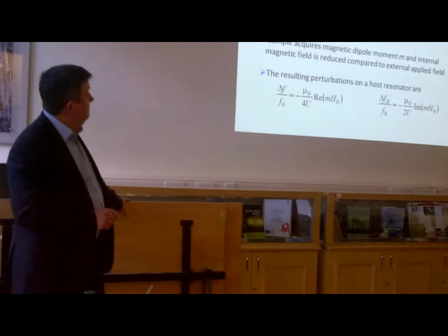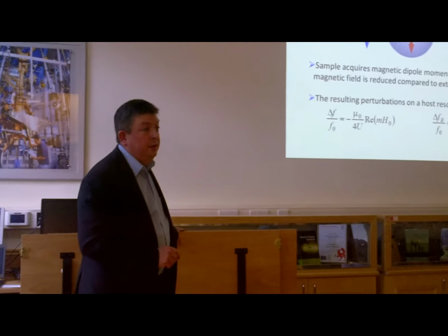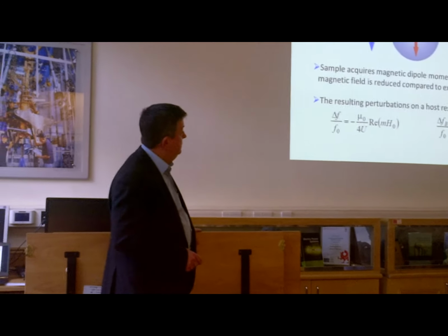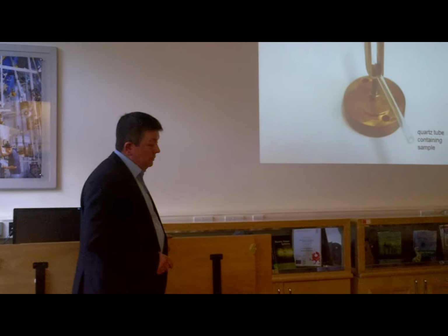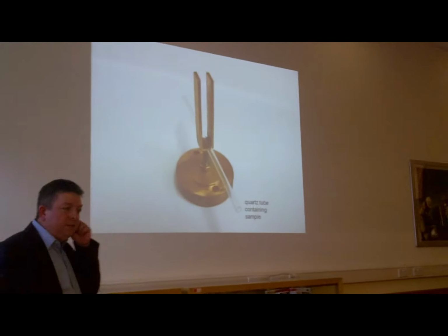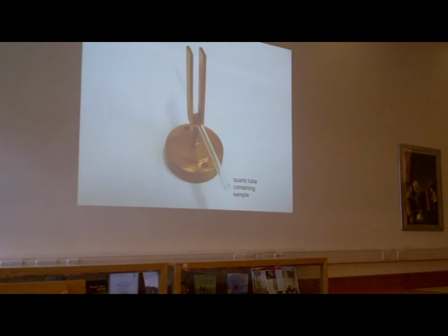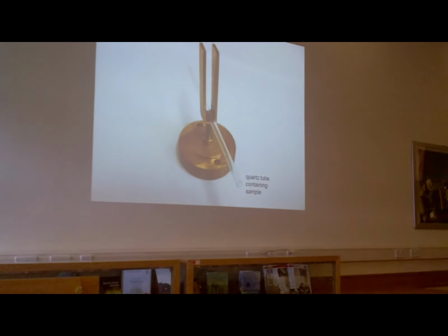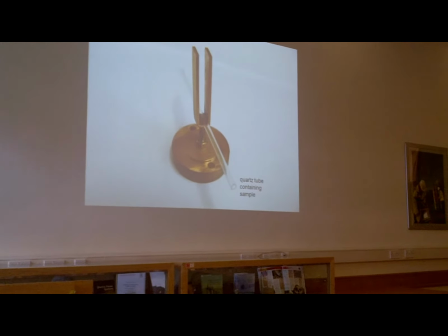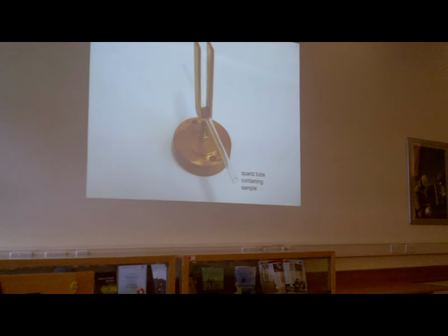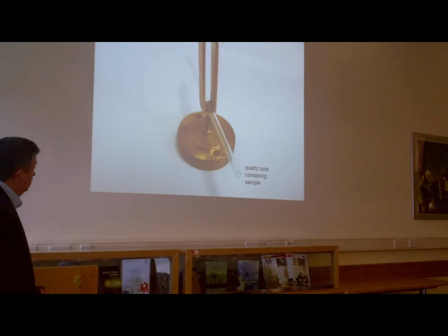Then lo and behold, you end up with very similar expressions for the cavity perturbations. The in-phase part of n times h tells you about the frequency shift, and the out-of-phase part of n times h tells you about the bandwidth change. So again, you just need a simple theory linking the dipole moment to the applied field, and then you're able to quantify that dipole moment, and hence work out the fundamental properties of that material.